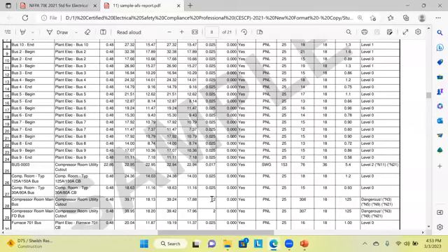Okay, what we can do is perform another simulation with different trip time settings and try to reduce it so that it won't cause nuisance tripping. Maybe he will reduce it to 1, then to other milliseconds. As you reduce it, the incident energy will reduce. So you can work with your consultant to reduce the incident energy available in your organization.